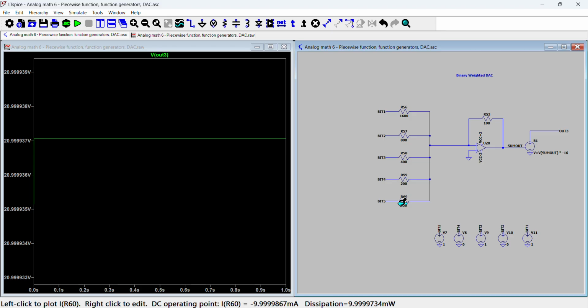And obviously, that's going to be really hard to manufacture because the accuracy of the adder is going to be dependent on the accuracy of these resistors relative to each other as well. And you're not going to be able to manufacture a resistor that's 100 ohms and then another one that's millions of ohms in the precision that's needed for a true binary adder.